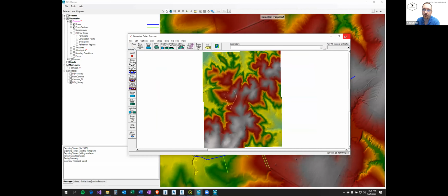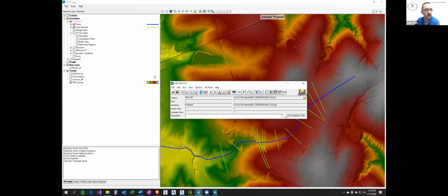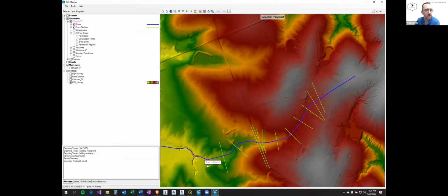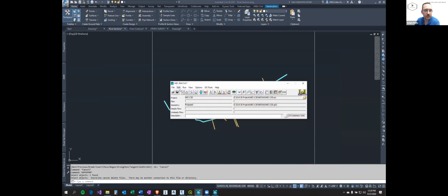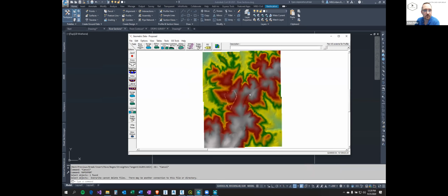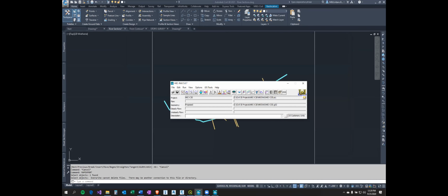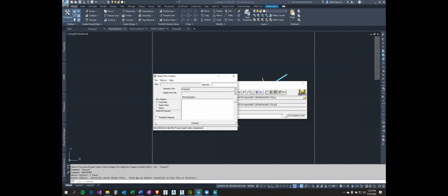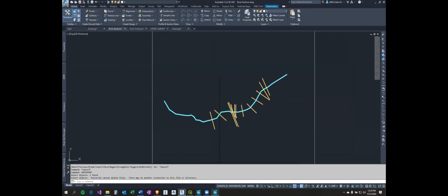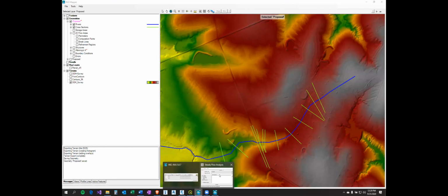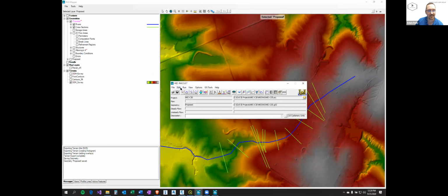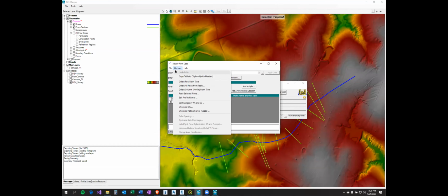That's odd. Any reason for that you can think of, Andy? Why it wouldn't have shown up here now? That happens sometimes. RAS can be a little finicky about it. If you create a flow file and a plan file, it should reconcile. You'll need a flow file first if you're going to try to run it. Yeah, that's RAS. So right there, it's not even picking it up.